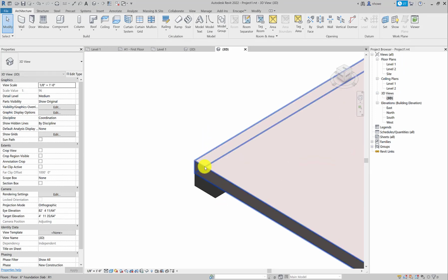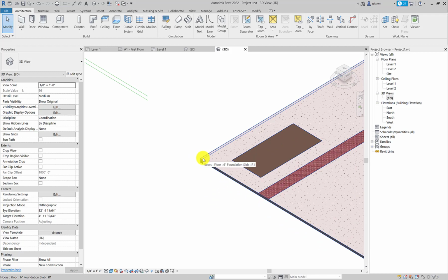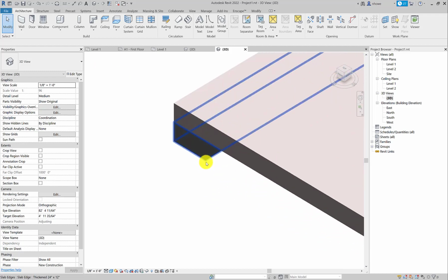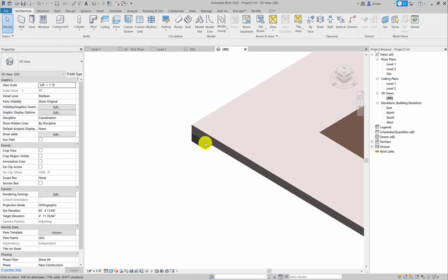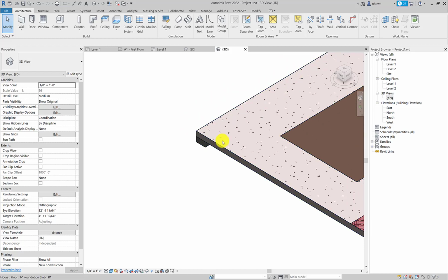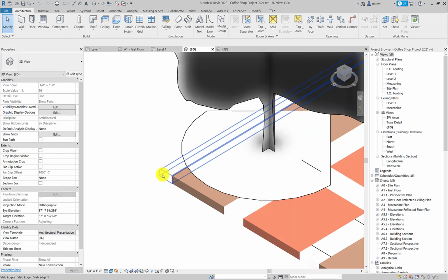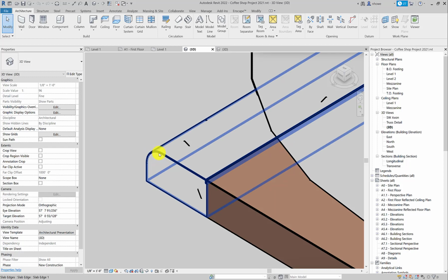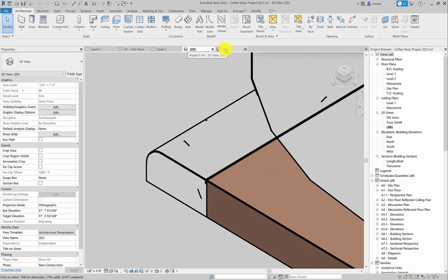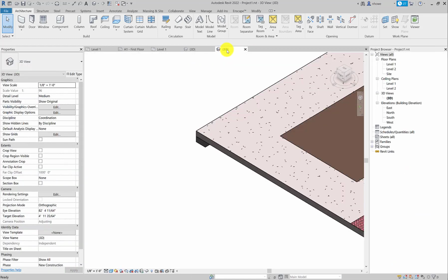So what it's doing is applying a profile to whatever edge you select. Obviously this just thickens it, so for concrete pours, when you're detailing it, you would be able to show that there's more concrete here at the edge to reinforce that part. But that's not really what we want to do, right? Because all we really want is this fillet here, at the edge of a curb. So what do we do there?